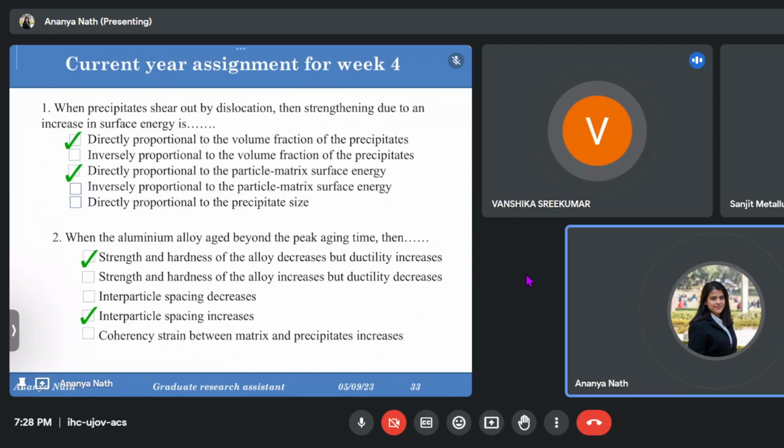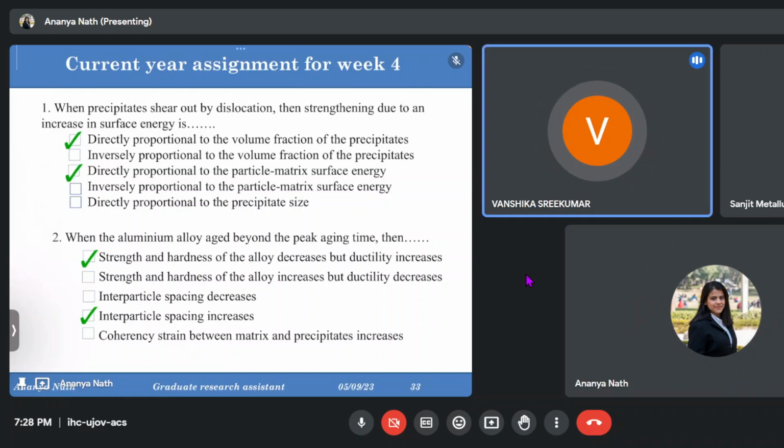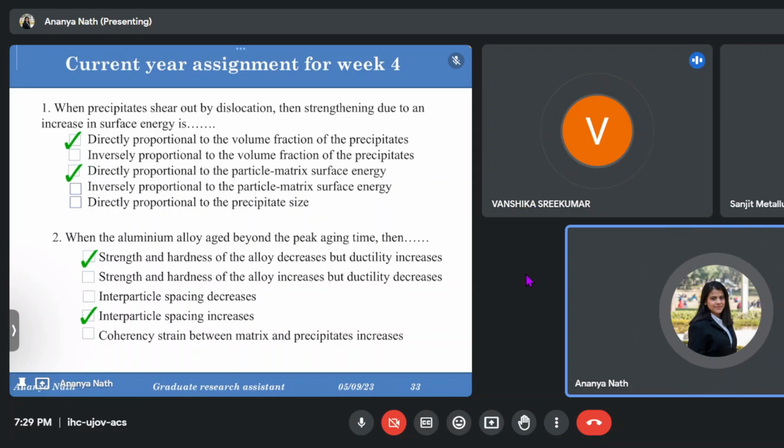Is there any selection, like if the parent lattice is FCC, then the precipitate has to be something? No, it depends upon which parent lattice and which solute atom is present, how they are bonding with each other, how much bonding energy and attraction they have. In that way they will get arranged in a particular lattice. But it's definite for a definite type of alloy element. Understood.